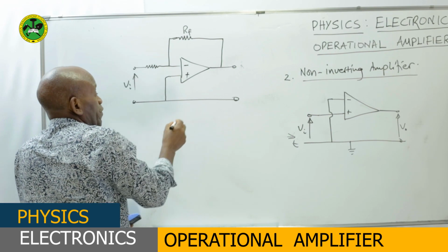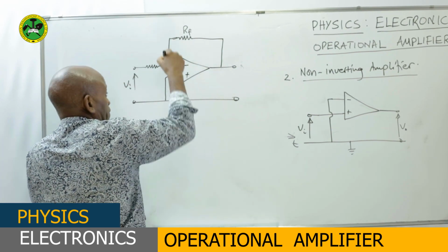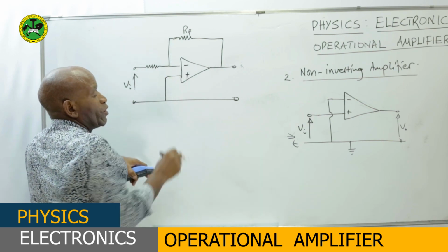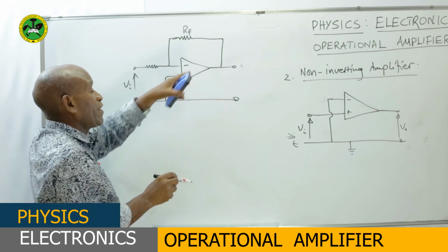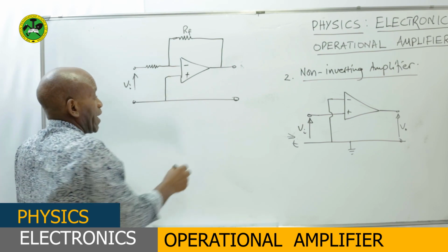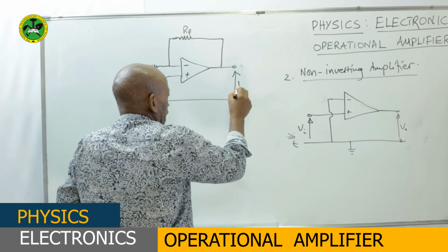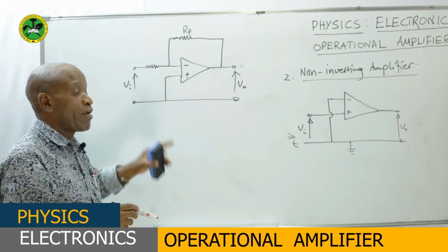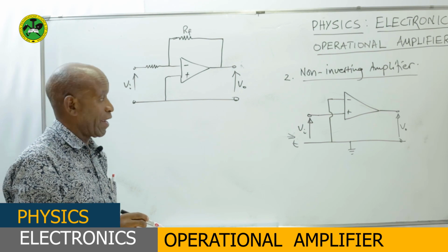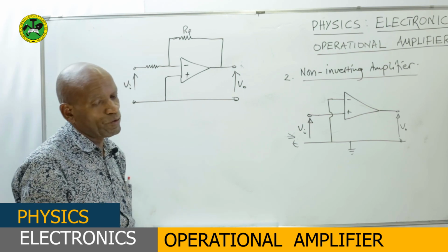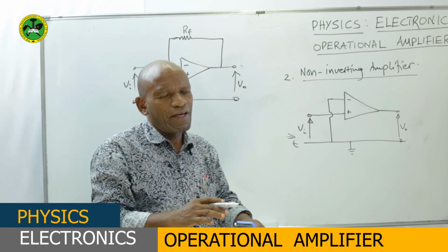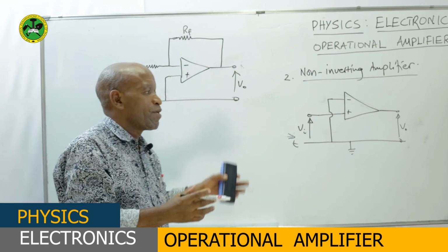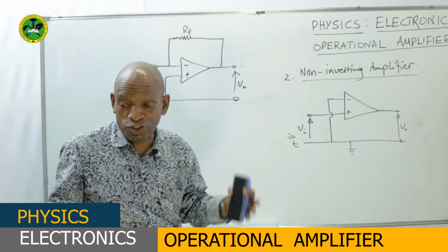This feedback signal passing through a feedback resistor will make the input signal to the inverting input terminal be reduced, and therefore affect the actual output voltage. When this is done, it affects the voltage gain of the operational amplifier. Depending upon the design, this can be very useful whenever a designer is using an operational amplifier for a certain purpose in an electrical circuit.